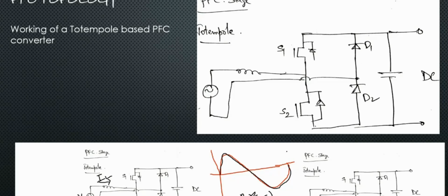So how does it happen? There needs to be a certain logic which is controlling it. We typically have something called a PID or a PI loop, which ensures that based on the reference voltage of the AC mains, the current is always flowing in a similar manner.